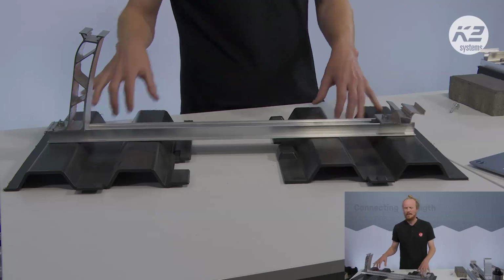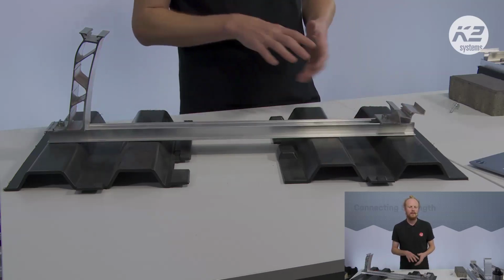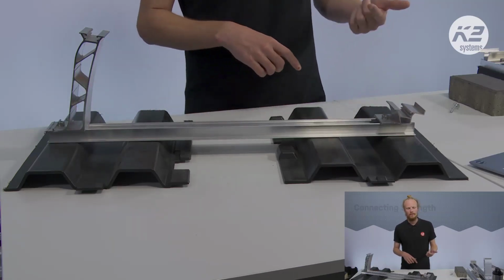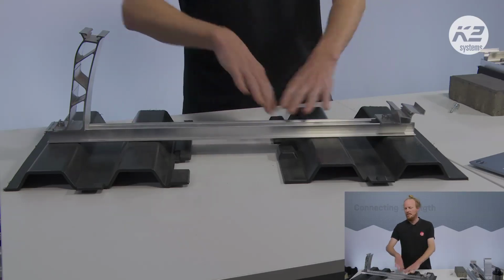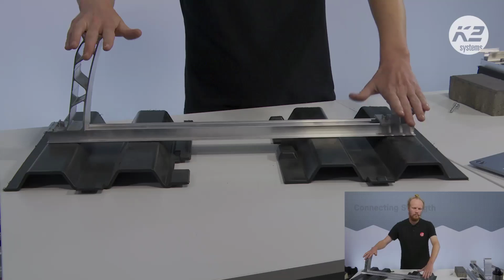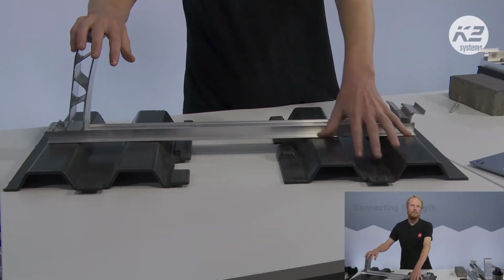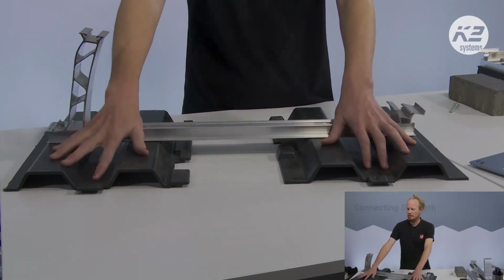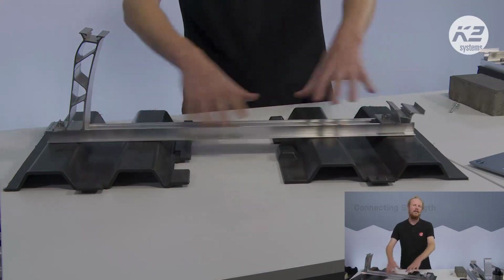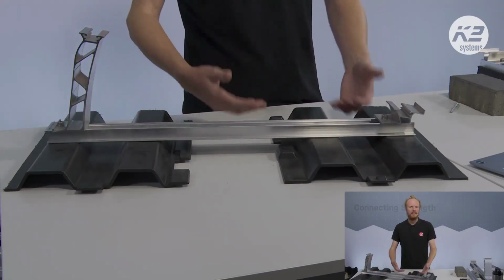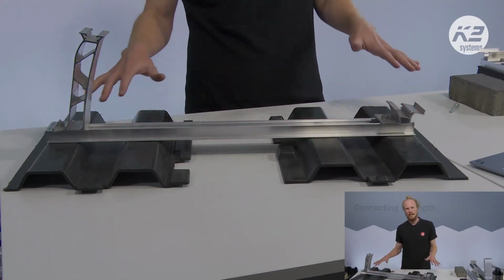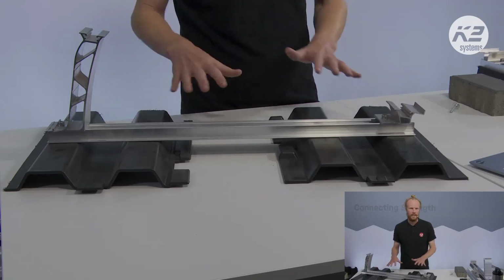So for every mat, we get an equivalent ballast value, and then that goes back into the software and says, all right, well, the base says that this module that's sitting here needs 20 kilos. I know that this mat is a representation of 20 kilos, and this is the representation of 20 kilos, then we don't need any extra ballast here. The existing roofing material is already weighing that down, and we're done.